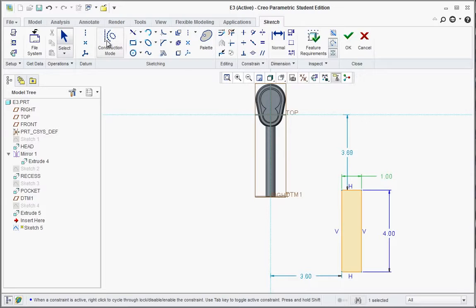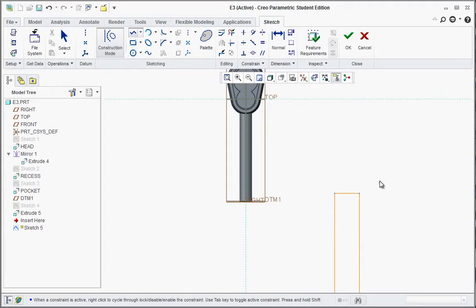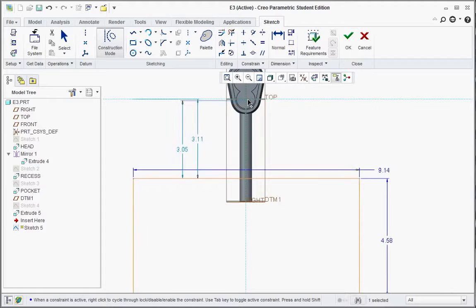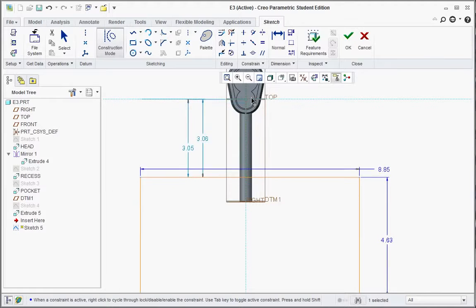Now what you can do is take construction mode here and draw a line at the midpoint. Look at that, that little M. So once you select the line tool here, in construction mode, you could draw from the midpoint a centerline vertically. Now the length doesn't matter so much, just go ahead and draw that out. But now middle click a couple times and grab that center point and drag it, and we want to actually lock that into the origin here.